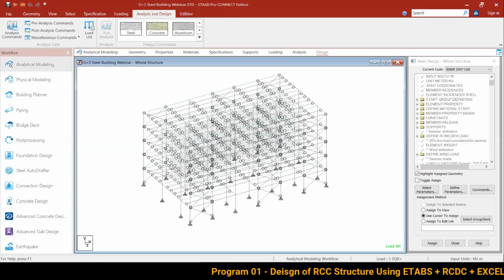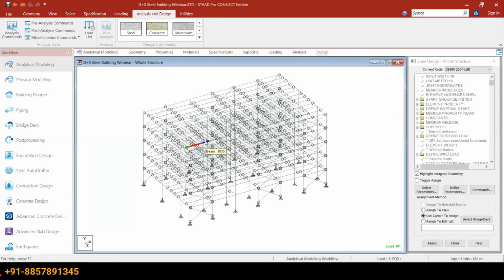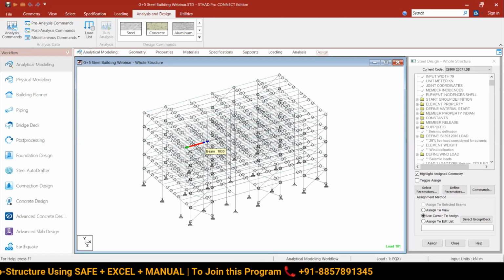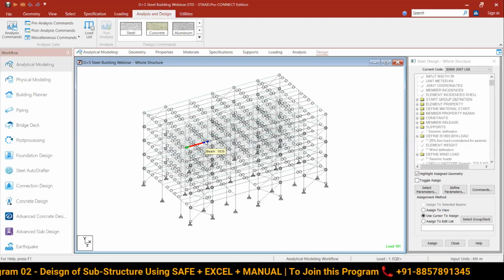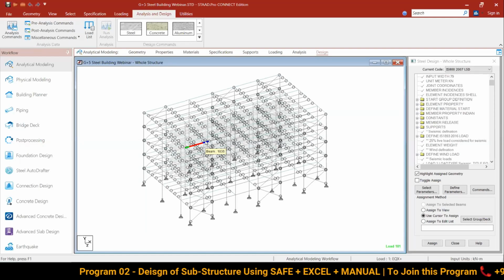And if I have a warehouse where along one direction I have my wall, but along the other direction my column is free to bend, then in that case LY will be different for the x direction, because in that direction I have my wall.